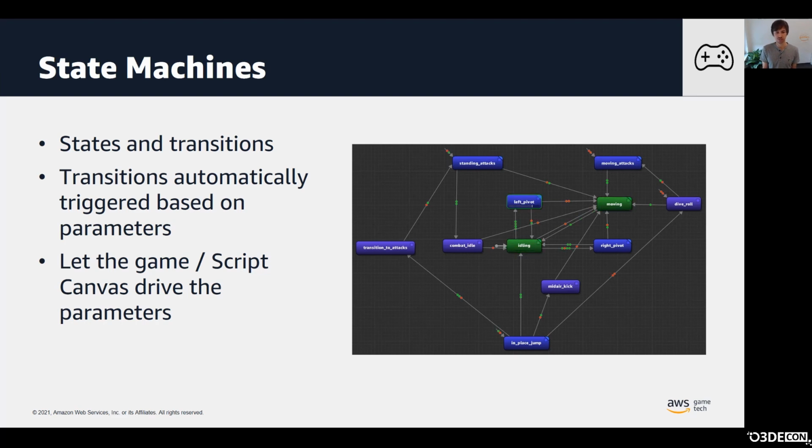If the conditions evaluate true, the blending process will be started and the green line on the transition indicates that process. Most of the time, a state machine has one active state, unless it's transitioning to another one, then two or even more might be active and evaluated.